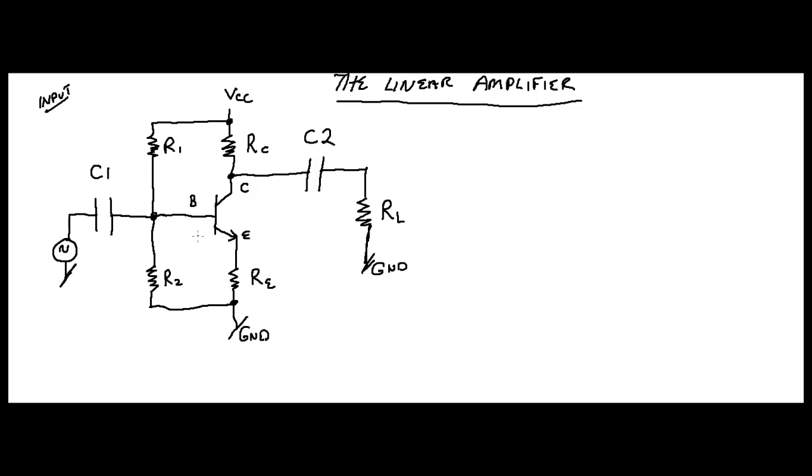All right, the capacitors ideally are seen as shorts to a signal voltage. So here's the other thing about a capacitor, right? Let's just write down what we just said, right? So for DC, a capacitor is seen as an open.